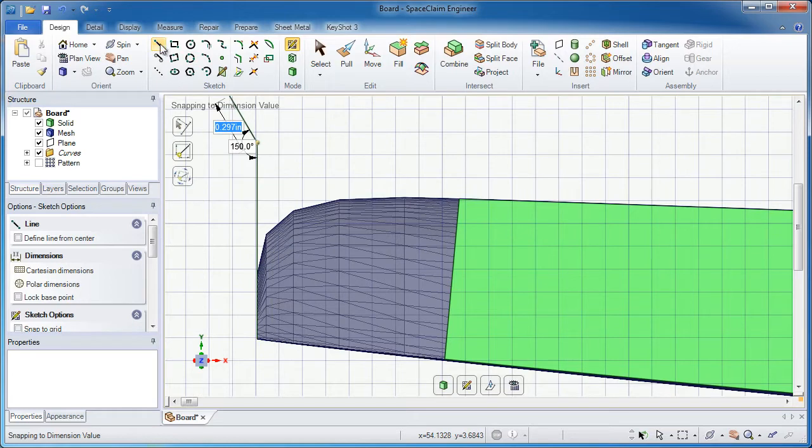couple of lines, a vertical line. I'll draw one right here, and I want it to be tangent, and so I can achieve tangency just like that by dragging it along the right direction. When I'm done with that, I'll connect a spline in the middle. Now the spline's going to start somewhere. This is around where it looks like it deviates from that line.